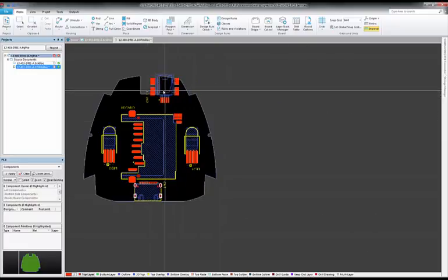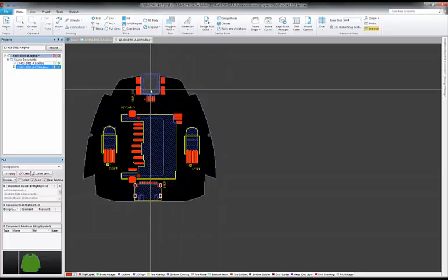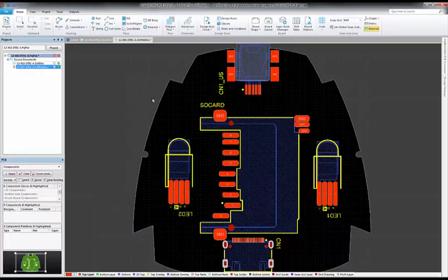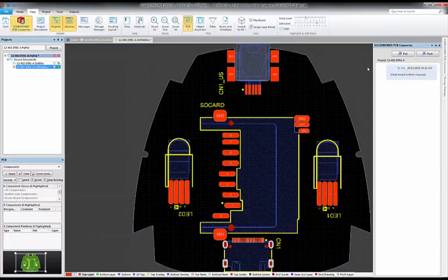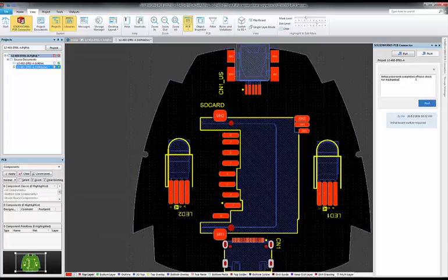our board outline, we can go through another iteration of the process by using the SOLIDWORKS PCB connector and pushing our board outline, now with the initially placed components on it, to ensure that we don't have any conflicts and that it does meet all the required fit, form, and function requirements.